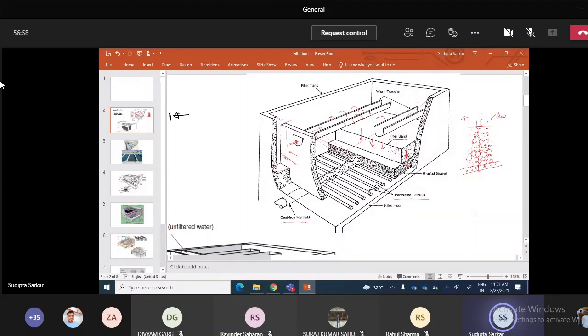So water will enter this pipe, travel through it and come to the manifold, and travel in the manifold and go out from here. So the dirty water comes here, passes through these beds, gets collected, and the manifold takes it out.